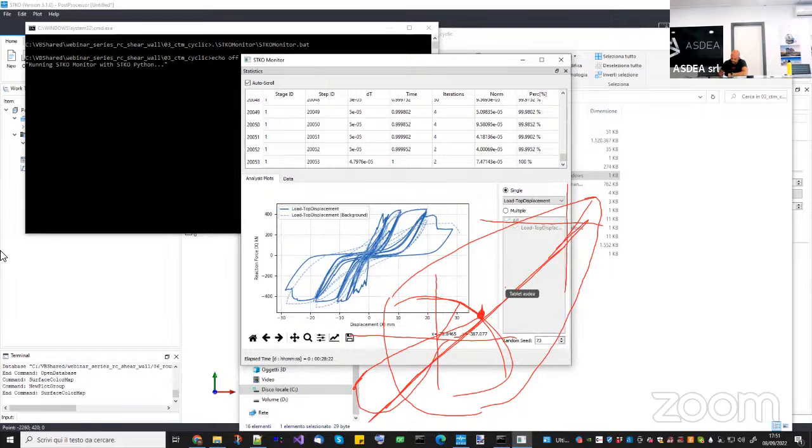Imagine I hit the surface at the beginning here. And then I'm unloading and I'm here. What is the next point? It is this one, but probably I will load in another direction and I will go here. So it's not so easy to define what the non-linear unloading path is to reach the other point, because the other point is not in a fixed direction. Instead, in a uniaxial model, you are in a fixed direction. So that's why it's a little bit easier to implement a non-linear loading and unloading rule.